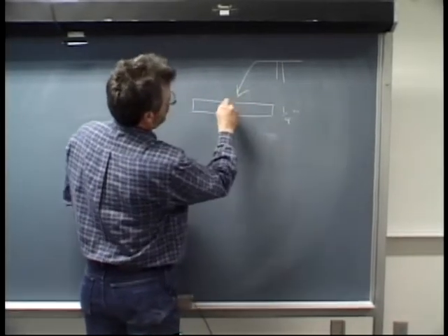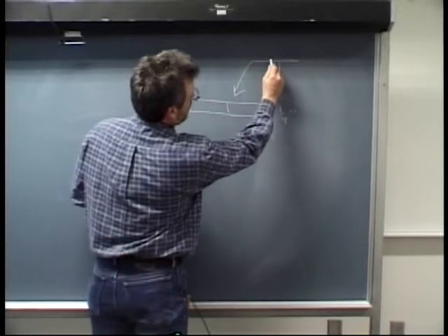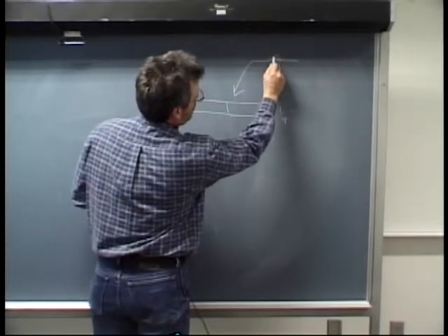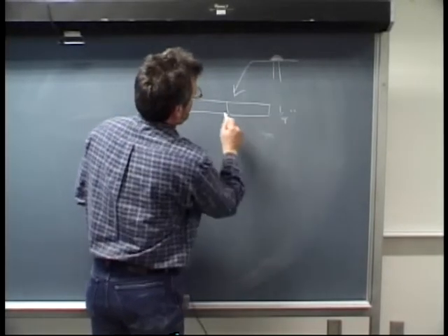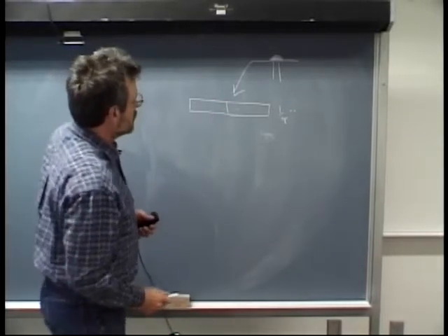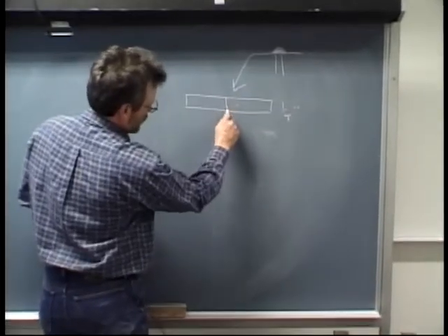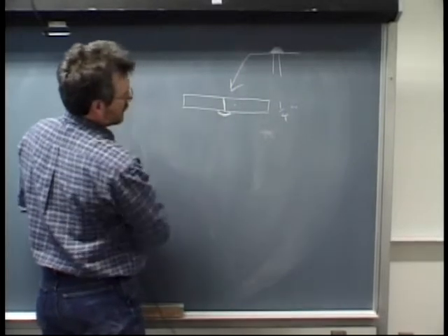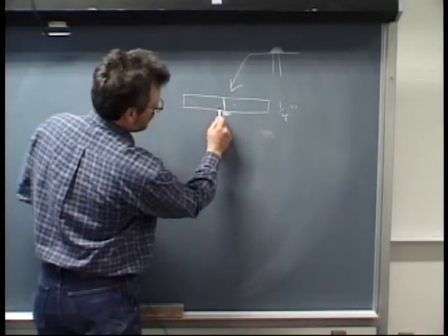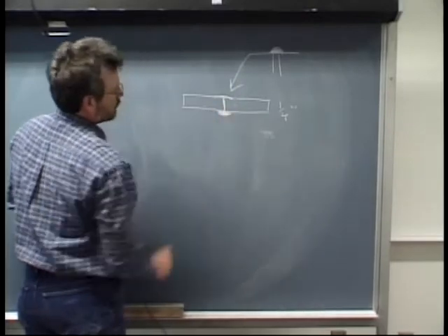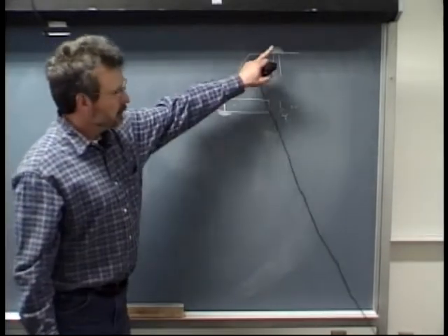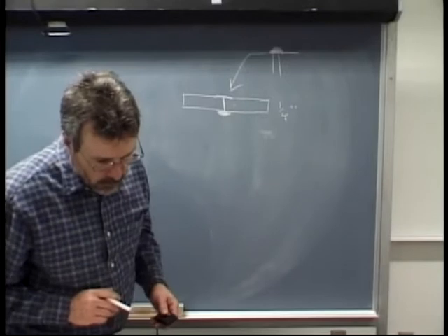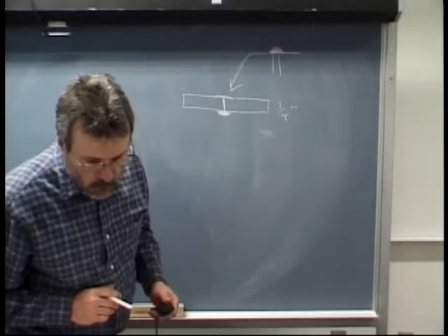Since the arrow side is here, on the back side they might do a melt-through symbol. So they're telling you that they want you to take this piece of 1/4 inch steel and make a square groove butt joint, but they want to make sure that you melt all the way through like that. And so your melt through is actually here on the other side, and then there's your weld. So again, if they darken it up, you know that they want you to get all the way through there.